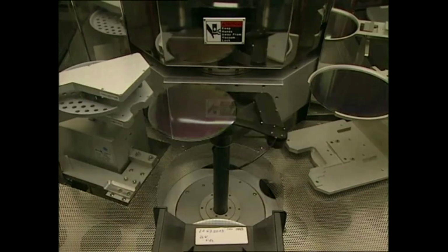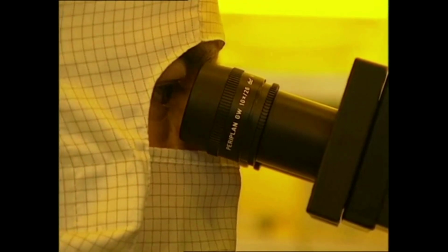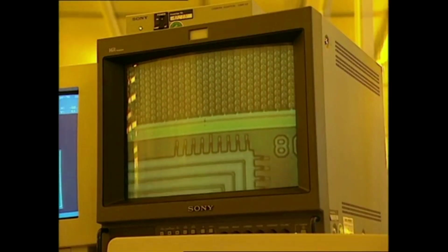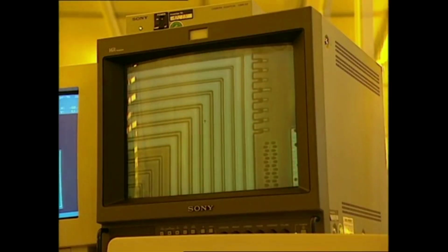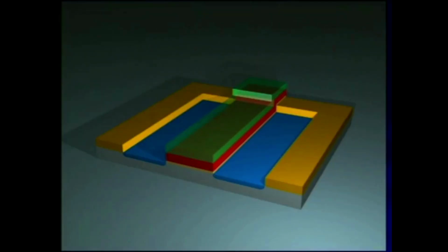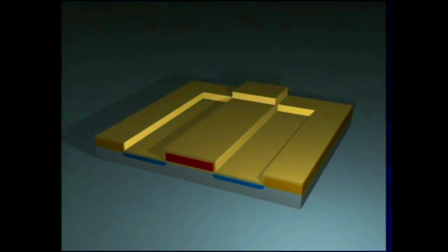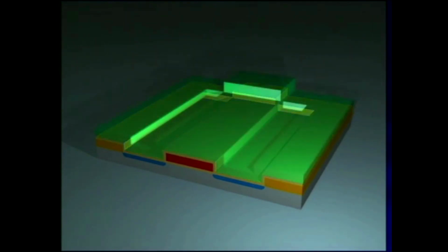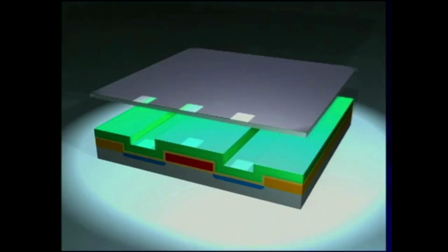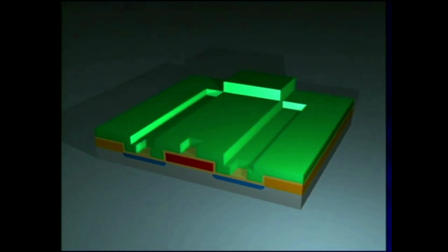In the next step, an ion implanter shoots impurity atoms into the silicon. This changes the conductivity of the exposed silicon by fractions of a micrometer. Structure, width, distance and cover precision are constantly checked. After the residual photoresist has been removed, another oxide layer is applied. Once again, the cycle of photoresist exposure, removal and dissolution takes place.